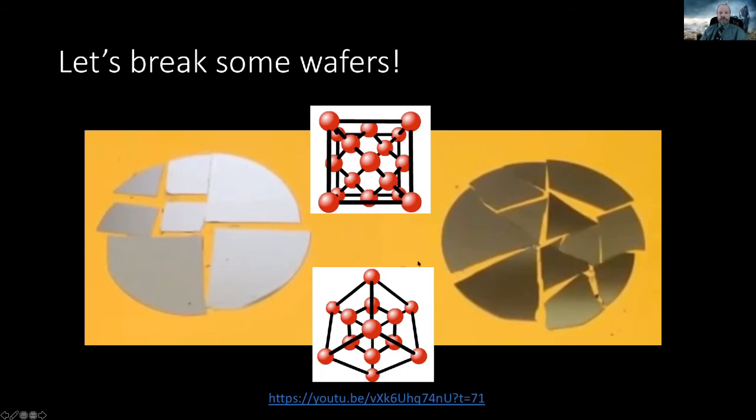All right. So why do we care about the crystal orientation? Different orientations will have different electrical properties and mechanical properties. You already saw the manifestation of the mechanical properties by how they break, how they cleave, right? But we're making computer chips on there. So it's mostly about how do the electrons flow in the crystal along that plane. So they'll flow differently. They'll have different conductivities and resistivities and whatnot, depending on the direction you're trying to get that current to flow.